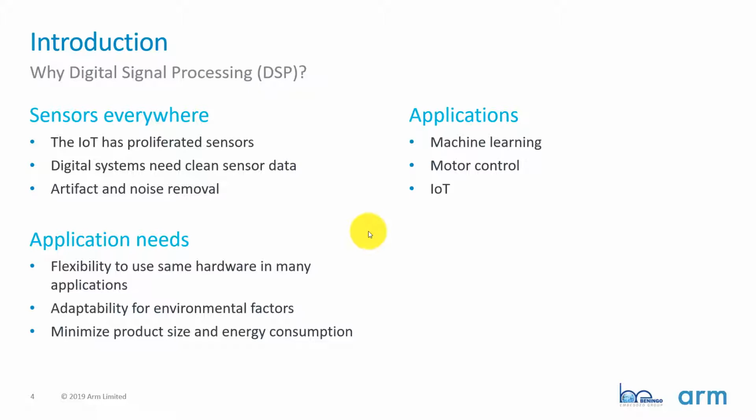We could first do it in hardware, which my last webinar, we actually talked about how you can decrease BOM costs by moving some of those hardware filters into software, which brings us to the second way of doing things, which is to do the signal processing in the actual microcontroller. Now, there's a lot of benefits to processing the signal data inside of our microcontroller. And we can do this using a special microcontroller that has digital signal processing extensions.